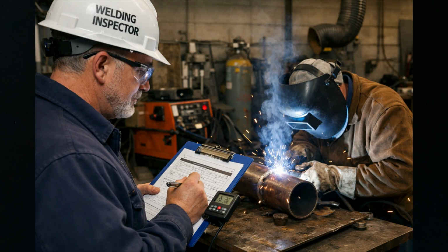Most importantly, the welding and the testing of the test piece shall be verified by the examiner or examining body. This is not something you can do on your own and sign off on yourself. A qualified, independent examiner, or a recognized examining body such as a certification authority, must witness and verify the process.